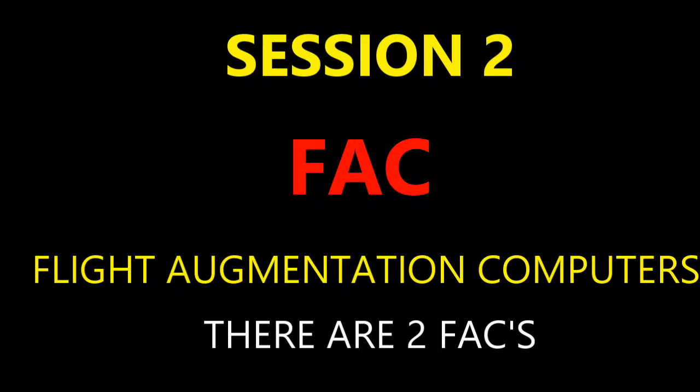All right, so the ELAC and FAC, remember I said as far as alpha floor and your wind shear protection, is computed by those two computers. What's going to trigger that? What is the magic number, the magic line there? If you have alpha protection condition and the side stick deflection at greater than 14 degrees, or you have a pitch angle that's greater than 25 degrees and the side stick deflection of greater than 14, this is the condition, and the alpha floor is available. Okay, so those are the following cases where you're going to have the triggering of the alpha floor.